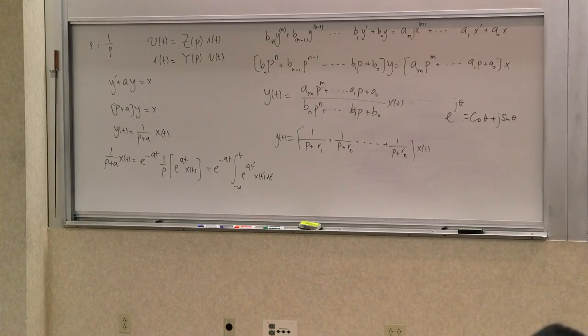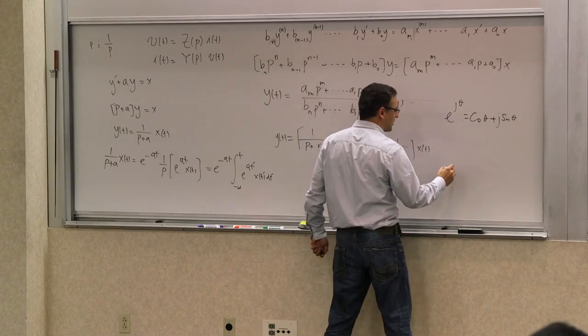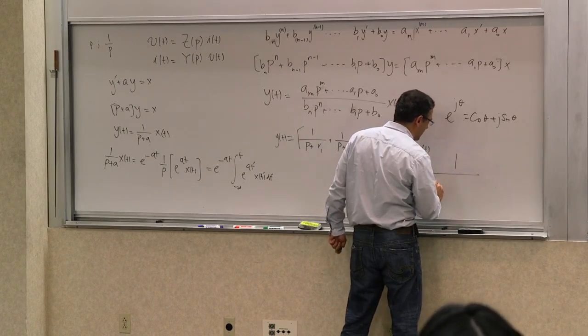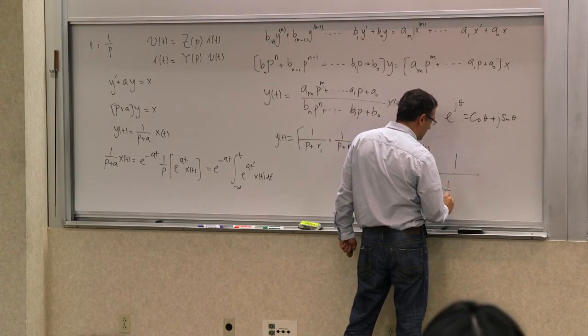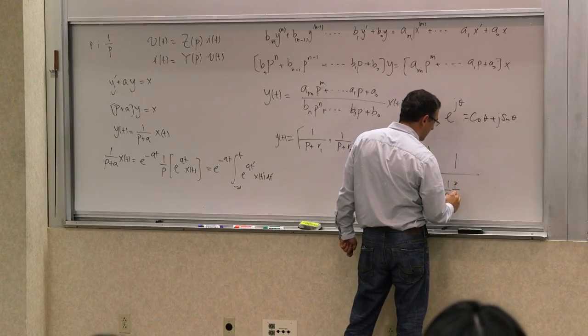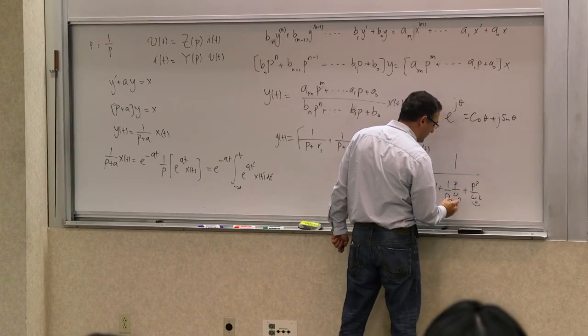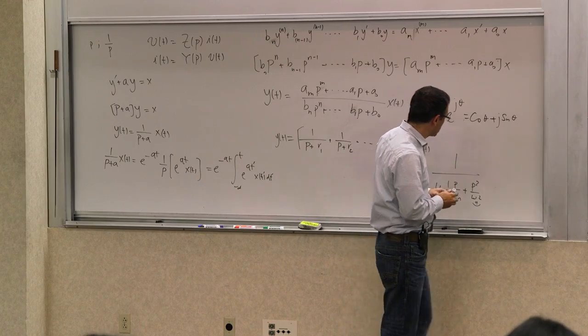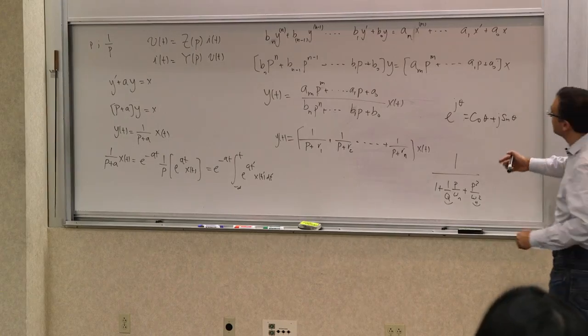We also dealt with second order systems in particular. There was some certain terminology for second order system which was quite helpful. You could write it as 1 plus 1 over q p over omega n plus p squared over omega n squared, and this was the natural frequency and this was the quality factor, so we could write them this way, and that allowed us to know what the properties and the transfer functions of these things are in terms of q and all that.